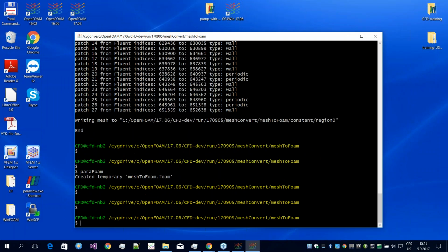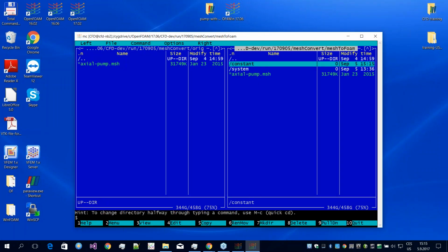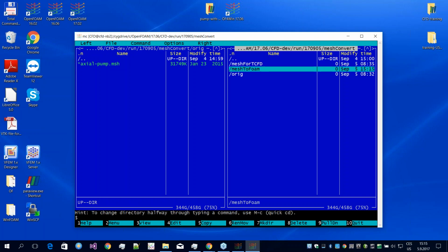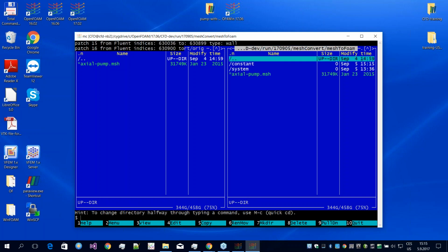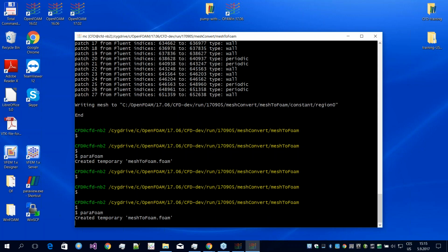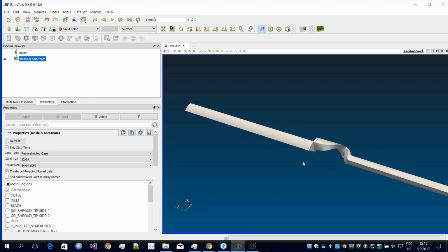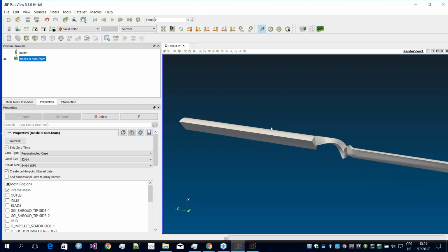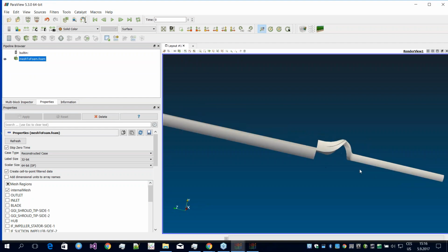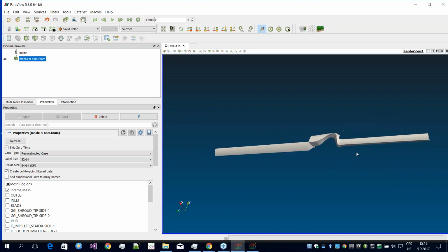Before I load it into our software, I need to split it into four parts. Maybe I was too fast, because this geometry consists of four separate parts. So first one is the inlet pipe, then we have the impeller, then we have the stator part, and outflow pipe.